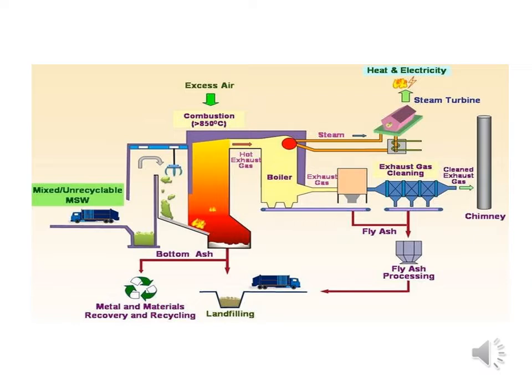After the pre-treatment process, the pre-treated solid waste is given to another tank. In that tank, homogenization takes place. There is a homogenizer and homogenization takes place inside that tank. Homogenization helps to create a stable emulsion, and with the help of this homogenization process we can feed a larger quantity of solid waste into the incinerator.